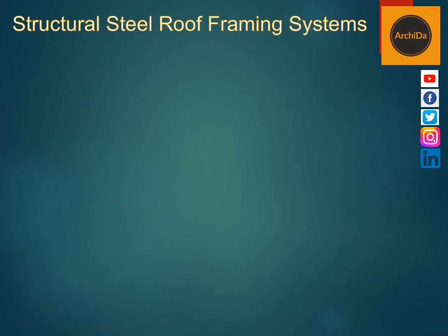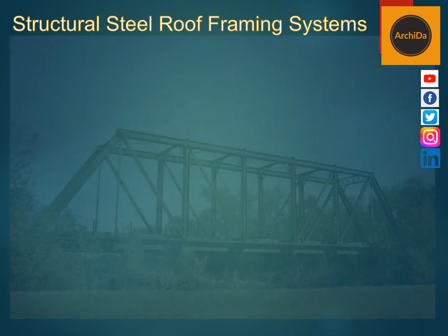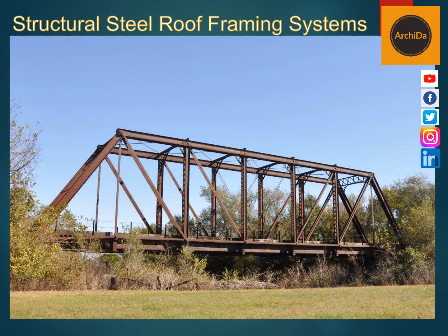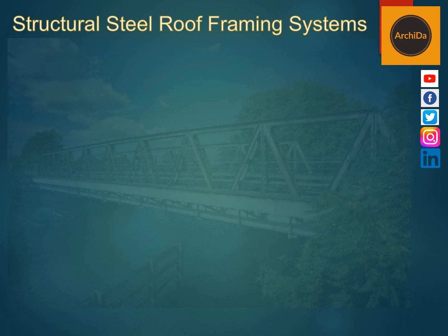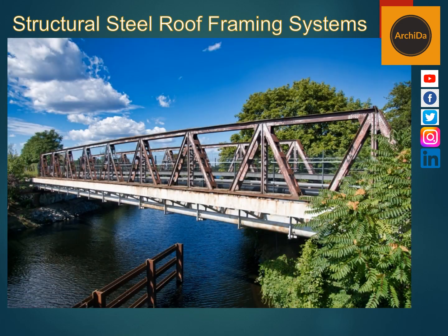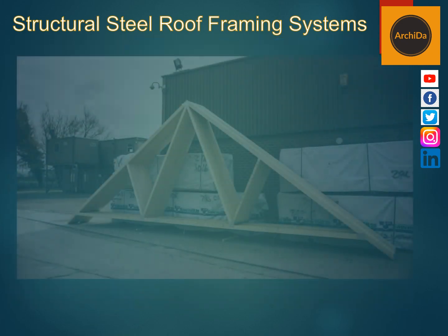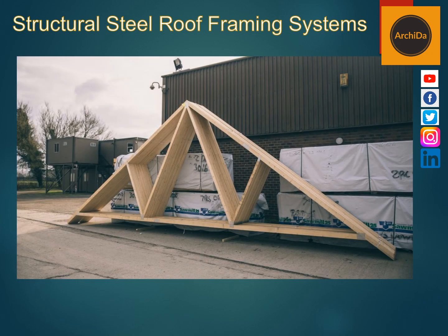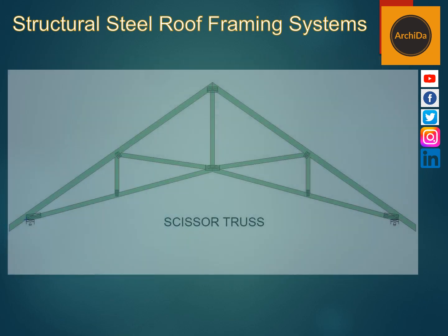Now about trusses. They can be used for the case where a restriction on the element depth is not imposed. It is an economical way of spanning long distances, provided that a depth limitation does not exist. Trusses are better compared with other options in controlling deflections due to better stiffness. Various types or configurations are the Pratt, Warren, Fink, Scissor, Bowstring, and Vierendeel.